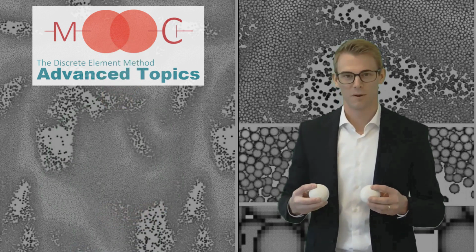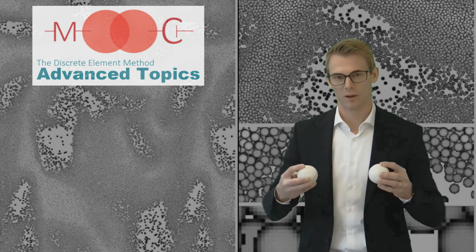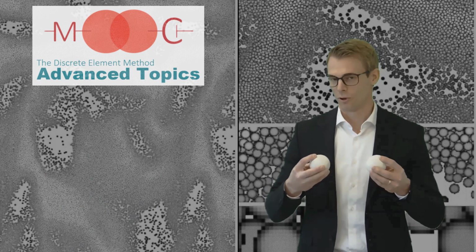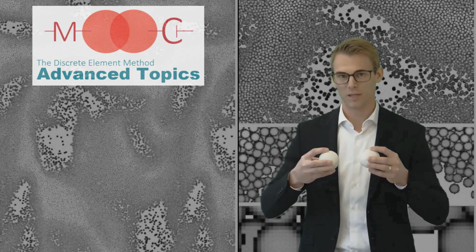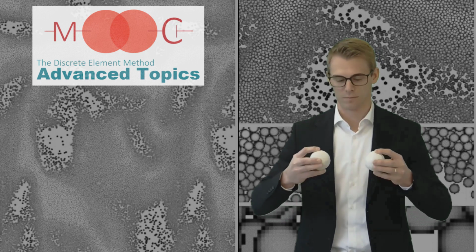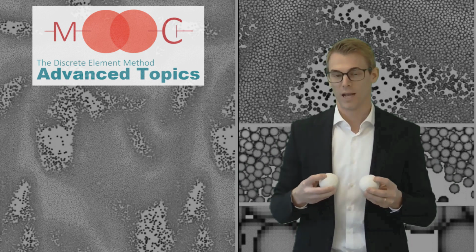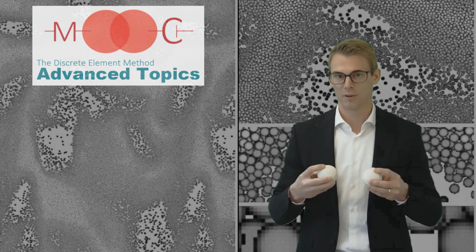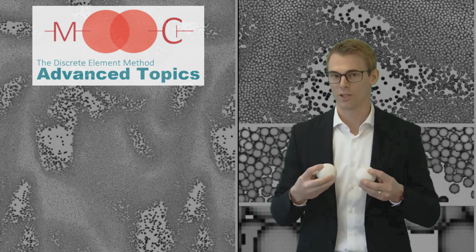Certainly. To set up a bonded particle model, an advanced contact model is used that is able to connect two particles with a beam-like element, so-called bonds or bondings. Those bonds are able to transmit loads between the particles, resulting in deformation effects or stresses, such as tension, bending, or torsion. And with that, the resulting structure, the bonded particle model, is able to react as a unified, flexible structure rather than a rigid object.